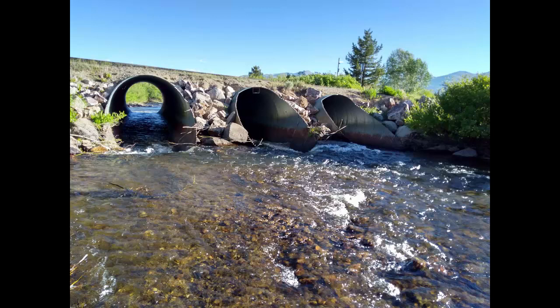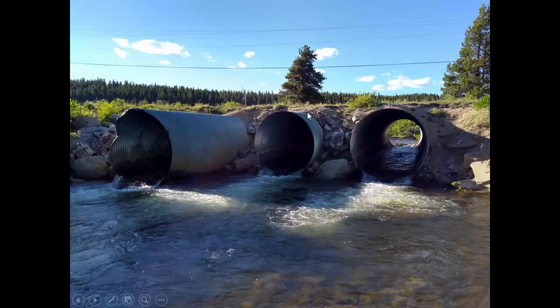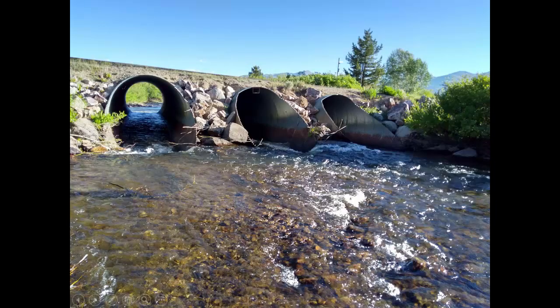Because we have such a vegetated state with lots of trees, and they just tend to accumulate too much trash upstream. We're upstream looking towards the downstream end here, so the water's flowing towards the culvert. So in West Virginia, it would be uncommon to have a multi-barrel culvert like this because logs would get stuck across the width like that.